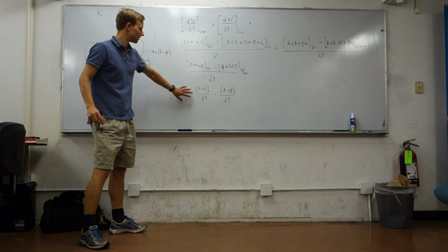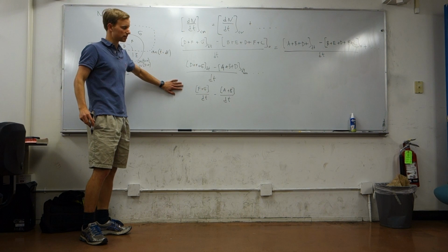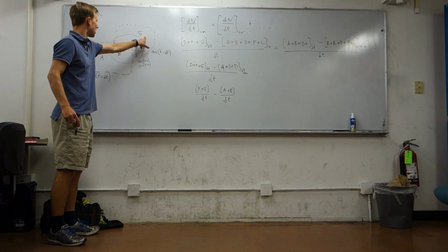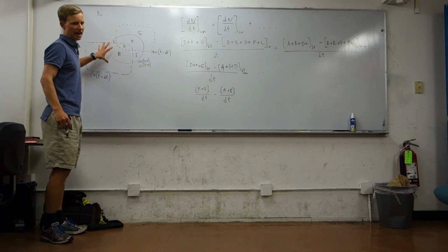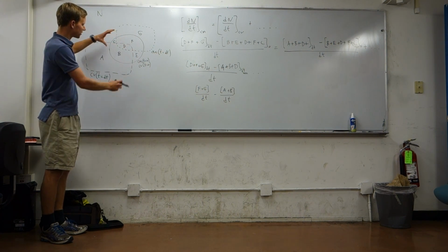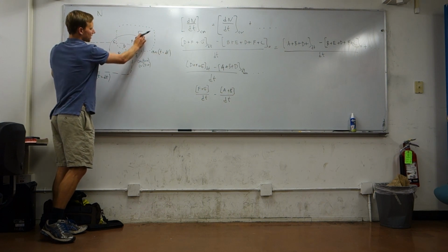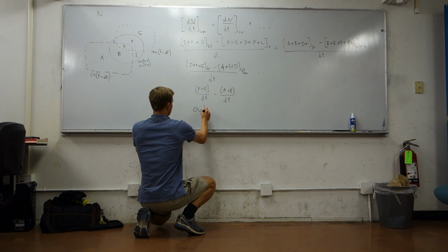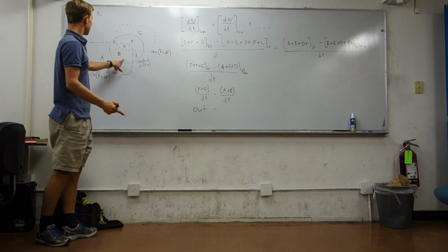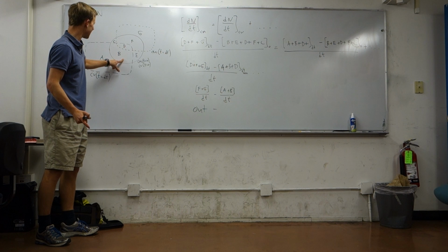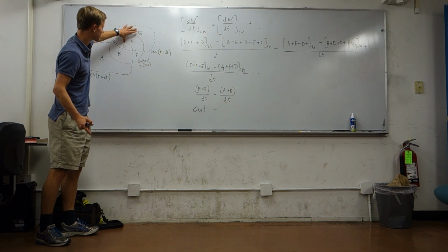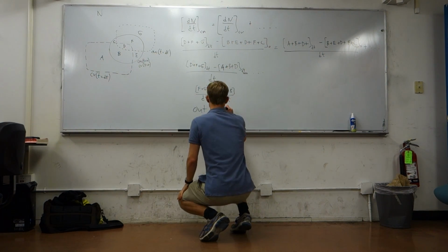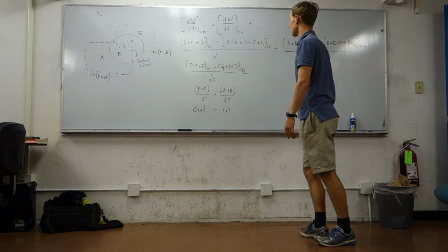Now, what do these terms actually mean? So we just did accounting, not just in terms of areas. F and G are the outflows from our control volume. Those are things that our control volume contained that now the control volume no longer has in it. So this is nothing more than our out minus, and then A plus B are things that the control volume has in it now, which the control mass does not have anymore. So these will be inflows into our control volume. Minus in. And so we're left with